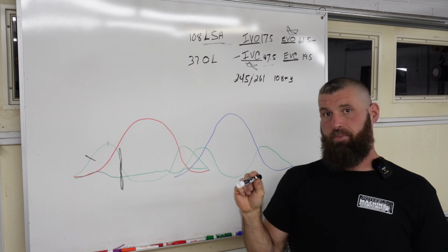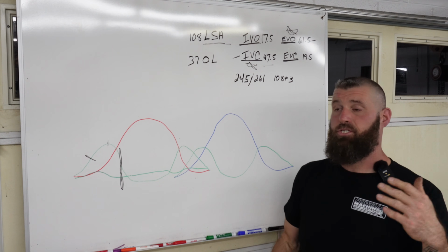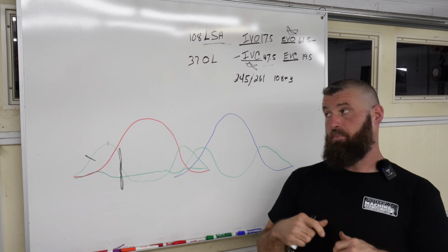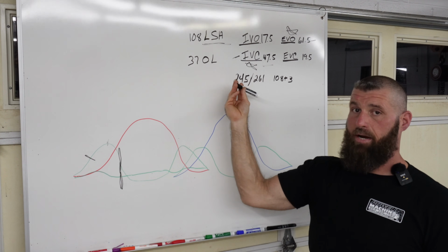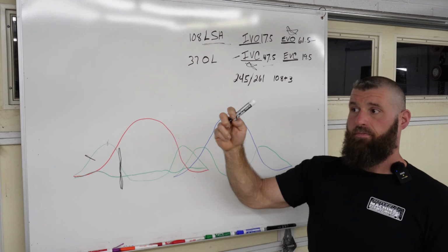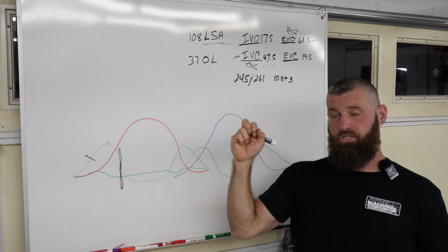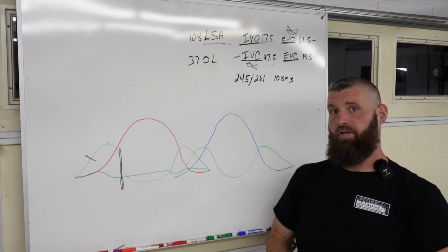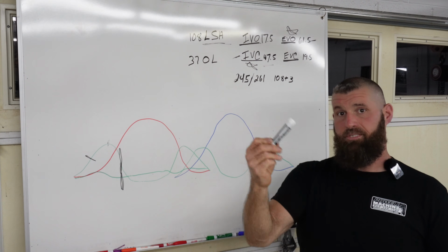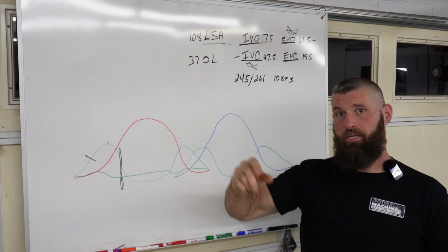You've got engine speed and you've got the speed of the air, especially on the intake. Even though the piston's coming up, there's so much air coming in, the speed of the air just overpowers the piston, so you can have more cylinder filling while the piston's coming up as RPM increases.